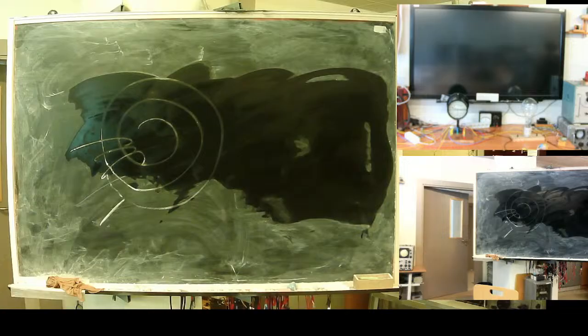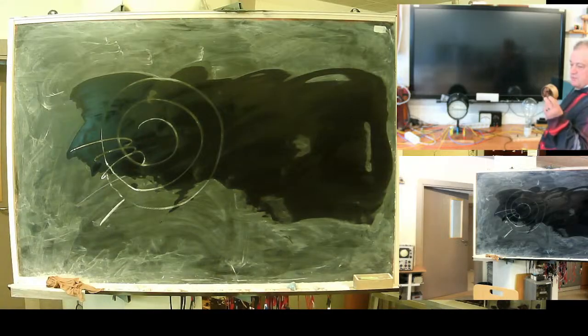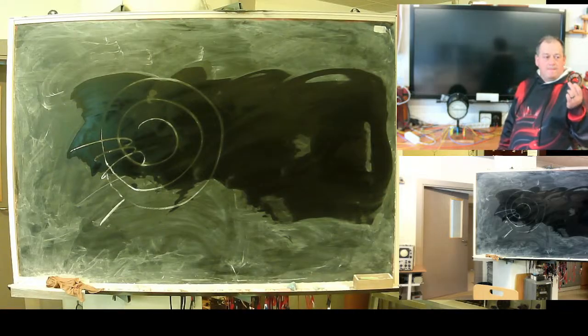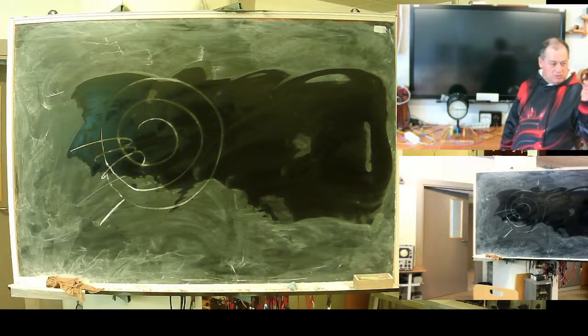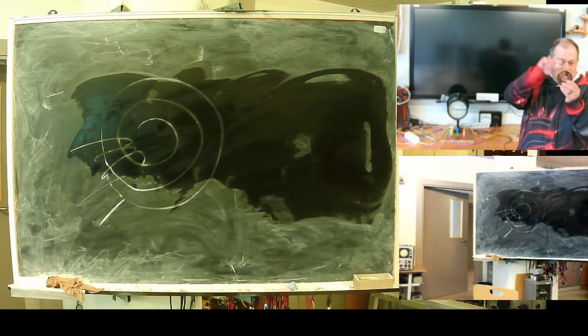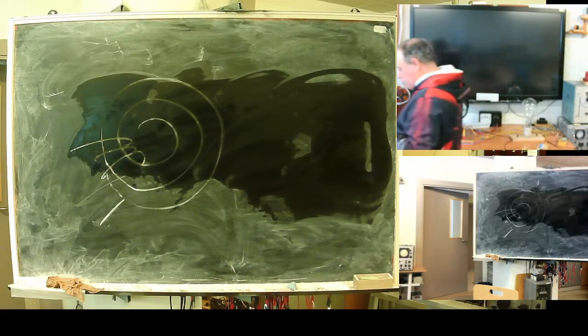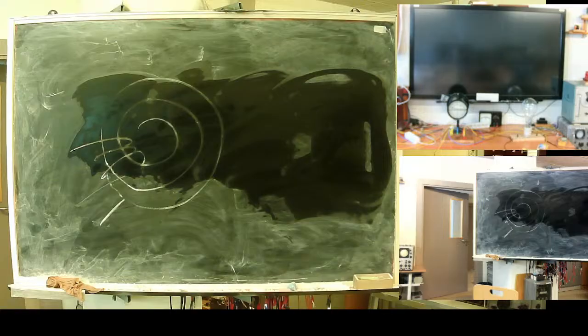This model is approximately, say, 10 times more expensive than one assembled from sheets. Because winding is relatively small, you need many more turns, and turning on a toroidal core. It's a toroidal transformer. What's good in a toroidal transformer? They have closed magnetic paths. But this toroidal transformer is much more expensive in manufacturing.